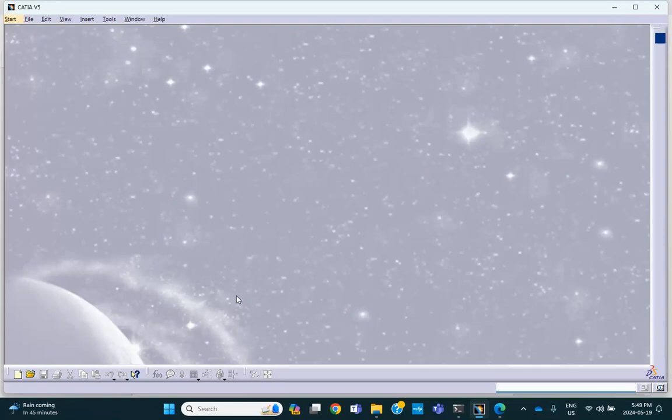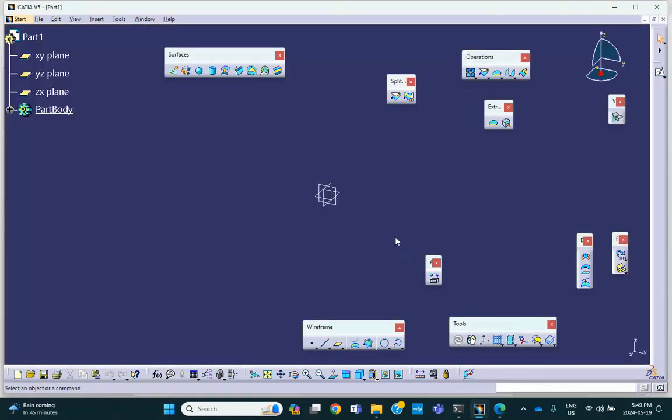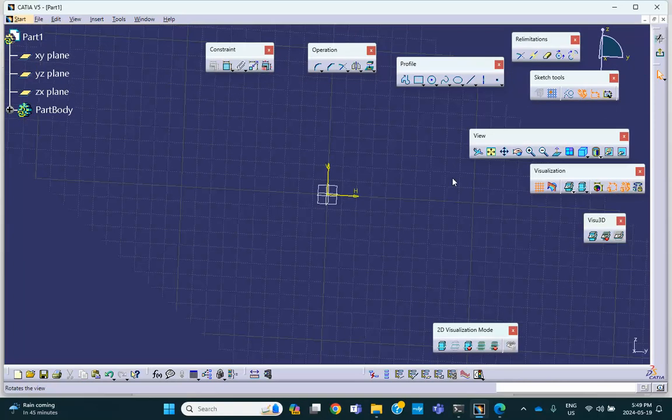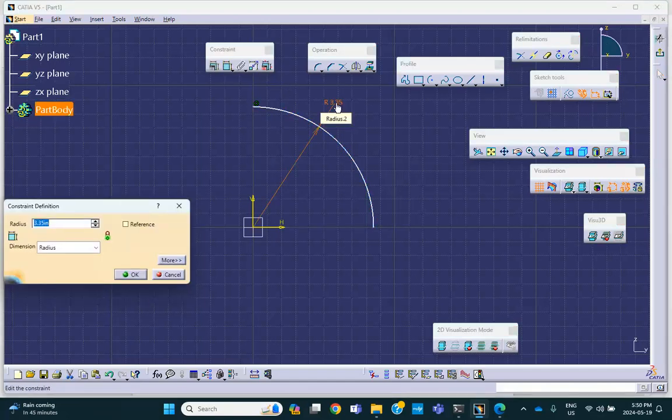The way I'm going to do that is generate that surface directly. So let's start with the part file. Instead of making a solid object and then extracting the surfaces and things like that, on that vertical plane, I will sketch. Okay, why don't I do a quarter of a circle? Here's the center, like that. Okay, and the dimension of this is 40 inches.